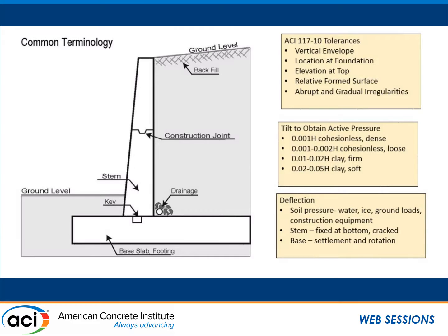And so I've looked at people on deflection calculations and said, what did you do about the water or the ice? Or, well, I used the soil design pressure. And I'm like, okay, well, that's an envelope of a bunch of different things. I said, what about the equipment behind it? Did it happen to add any pressure when it was compacting the stuff? No. Well, we think no. Okay.